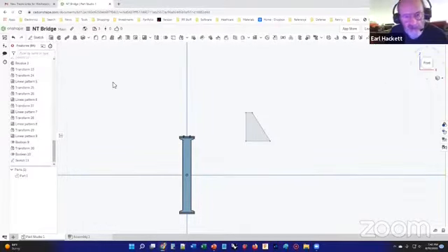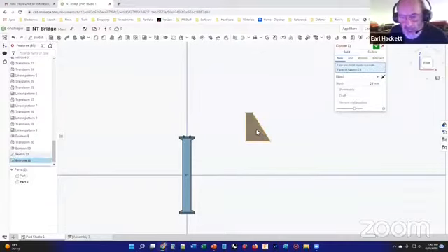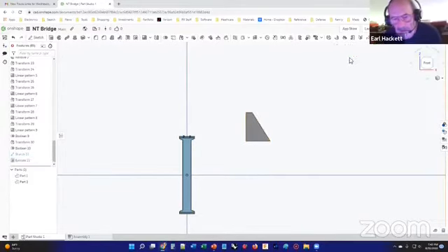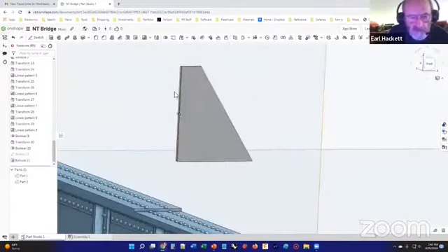And we're going to extrude this. And I'm going to extrude this to be fairly thick. I'm going to extrude it to 0.4 of a millimeter. Because this really is a structural piece, and this isn't steel. This is just plastic. So let's just check on it. That looks good. Go back to the front.